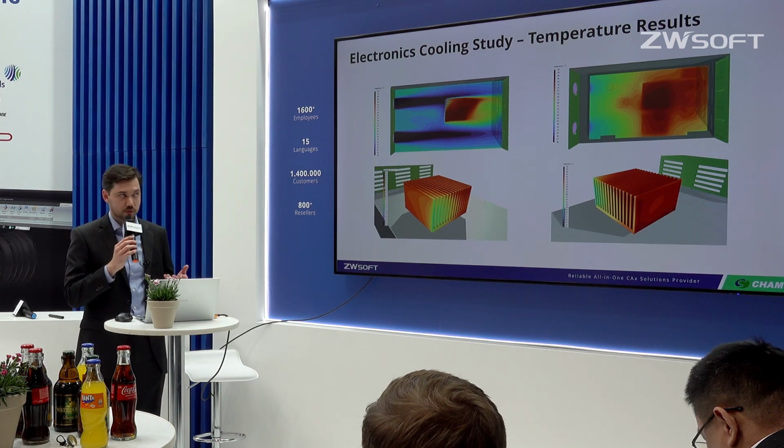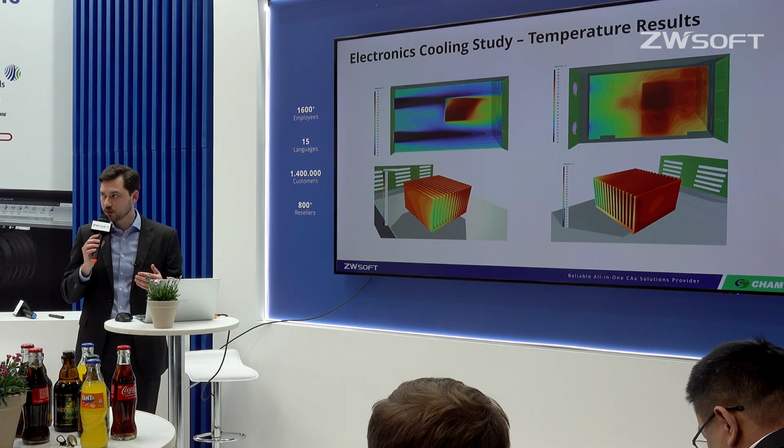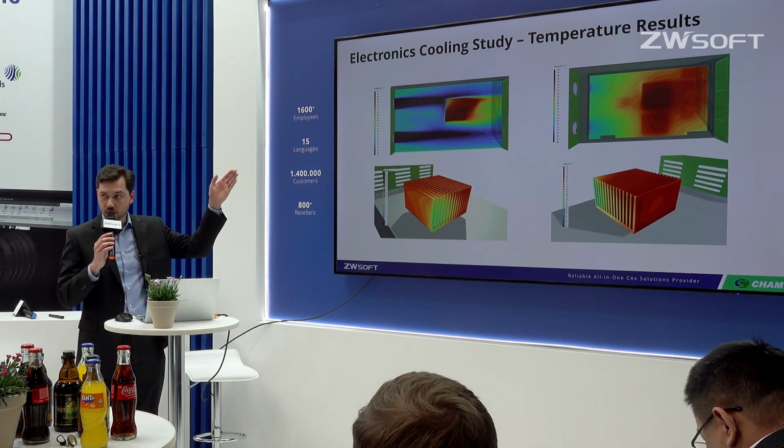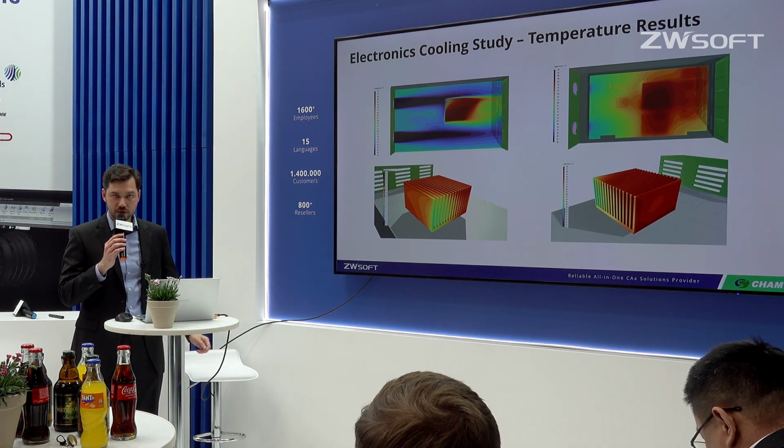The heat cannot leave. In the top section where we saw that the jet was interacting with the heatsink, there is actually a gradient. We see the color go from dark blue, signifying cold, all the way up to dark red, signifying hot. So whenever we see a gradient, that means that the temperature change is taking place. And in this case, that reflects temperature being removed.